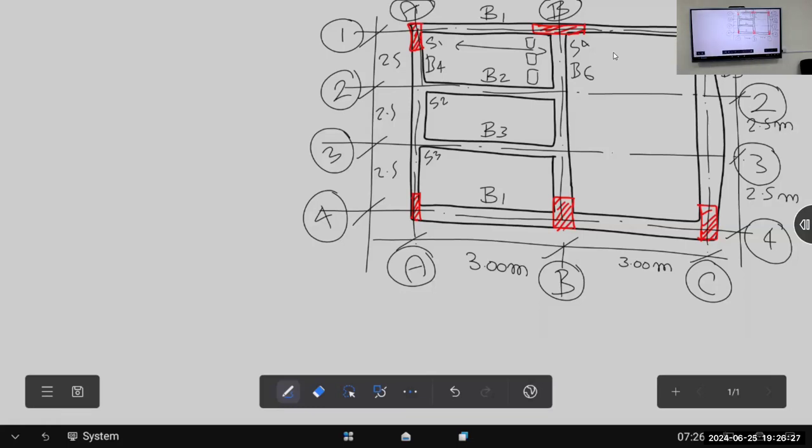Okay. Again, we come back to the effect. The loads will affect the slab in normal force, shear, and moment. The slab itself could bend under your load, for sure, 100%. Who will carry this load? The steel and the concrete. Concrete and steel. It is not the beam. Then the slab transfers this load to the beam. But there is an effect on the slab.